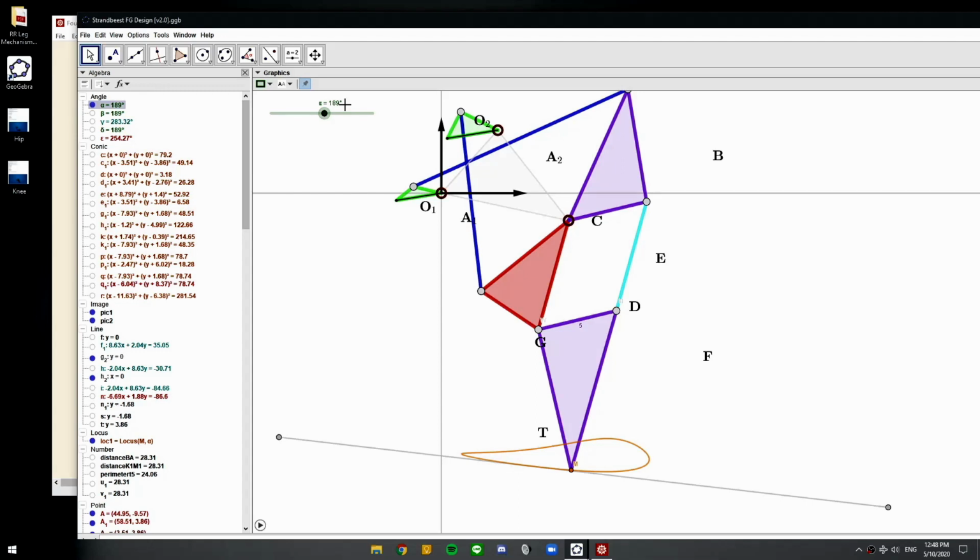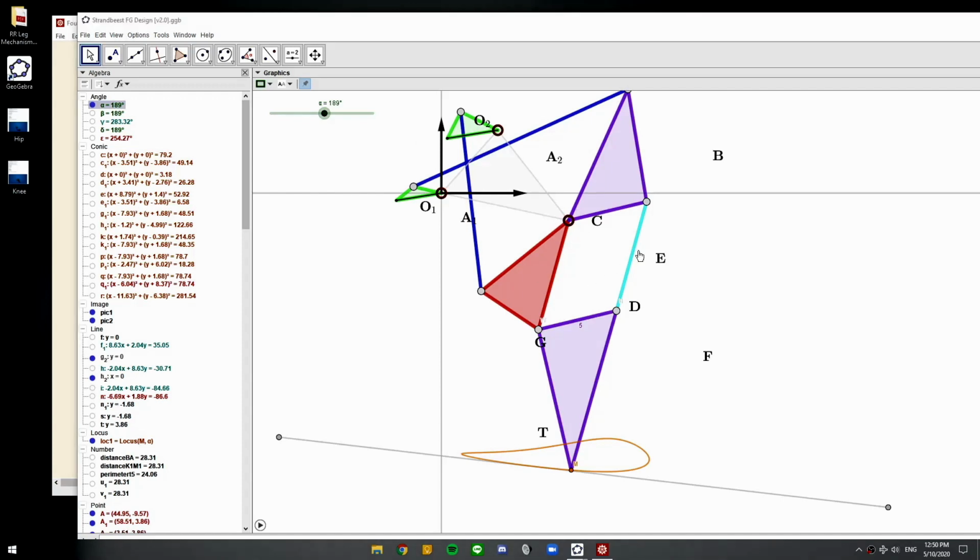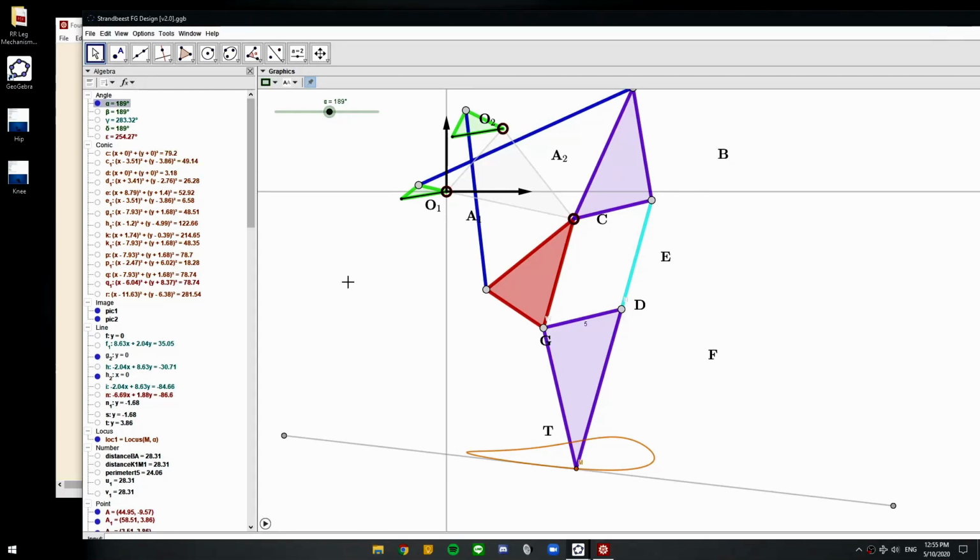at 1 point. Now when you're building this is just like the animation Professor McCarthy showed you guys at the beginning of the quarter, where we use 3 gears, 1 attached to the motor and 1 attached to this crank, 1 attached to this crank to drive the leg. So basically what you're doing is attaching the motor to 2 gears, so they drive these 2 cranks in sync. Alright, now let's go back.